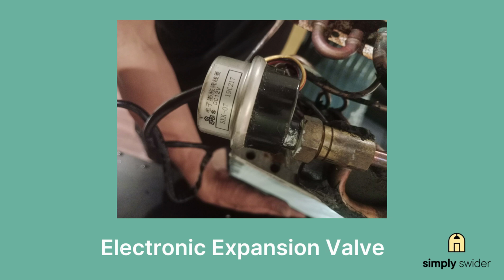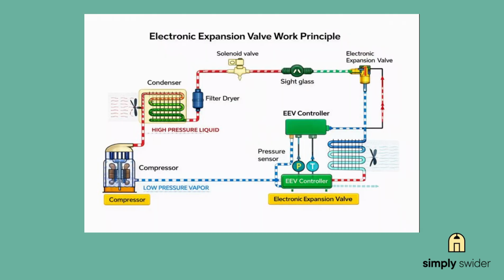Next up is the electronic expansion valve, or EEV. This little guy regulates refrigerant flow into your evaporator coil. When it fails in the closed position, it's like having a clogged artery. Refrigerant can't flow, so no cooling happens. I remember this lady who had a newer Samsung unit that would start up fine but never cool down. Took me about 2 minutes to figure out the EEV was stuck closed.